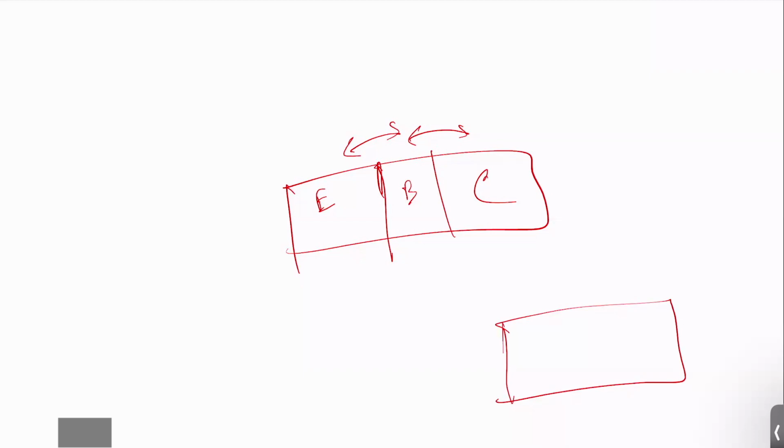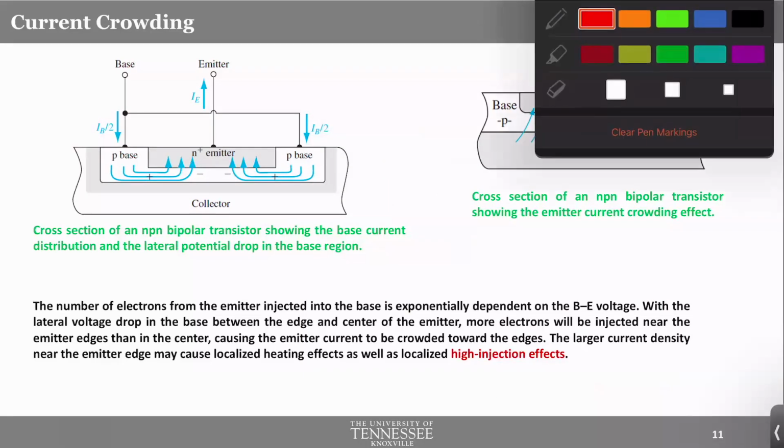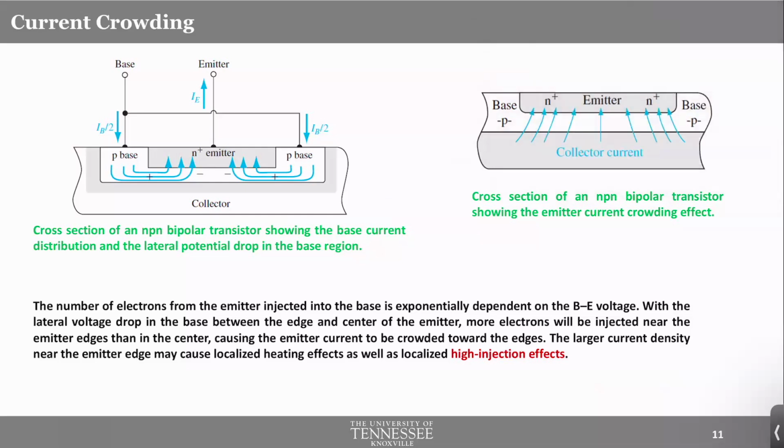bottom up. So meaning you first create the collector, which is the least densely doped layer. This is the collector layer, and on top of it, you create a p-type base layer, and on top of it you create an emitter layer by doping over and over again on top of each other. Okay, so that's how you create from the bottom up. So you have one layer, and within that layer you create a different layer, and within that layer you create the other layer. That's how you make the pn junctions. That's why BJTs look like this.